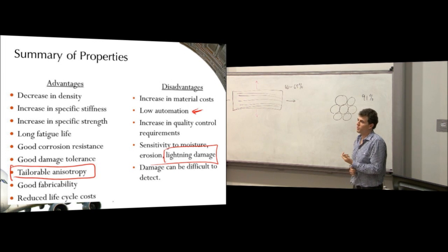So they've solved that by putting copper meshes into aircraft when they make them out of carbon fibre. They've got a very, very fine copper mesh between some of the layers that they put in, and that makes the structure much more conductive and can dissipate those lightning strike problems.